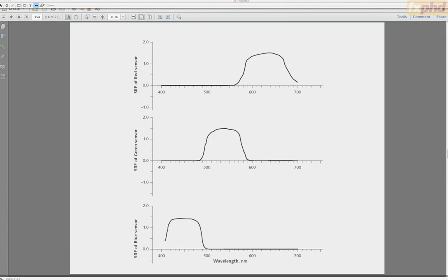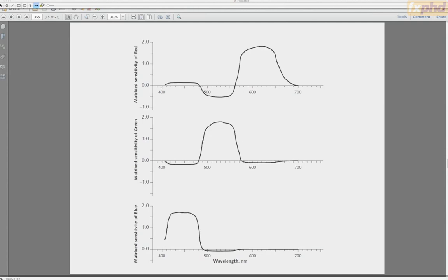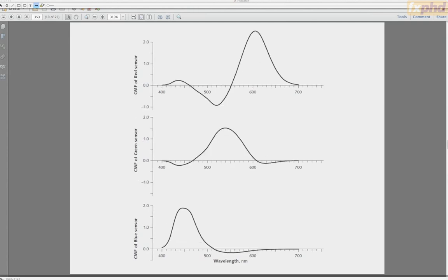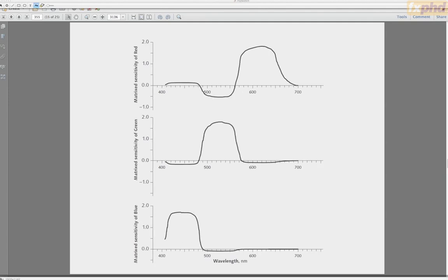This is an example of a Sony 3CCD dichroic set. And you use electronic circuits to mix those in the correct proportions so that they resemble the ideal theoretical curves. And that is what the 3x3 matrix does. And how you make the 3x3 matrix, we'll do that next class.